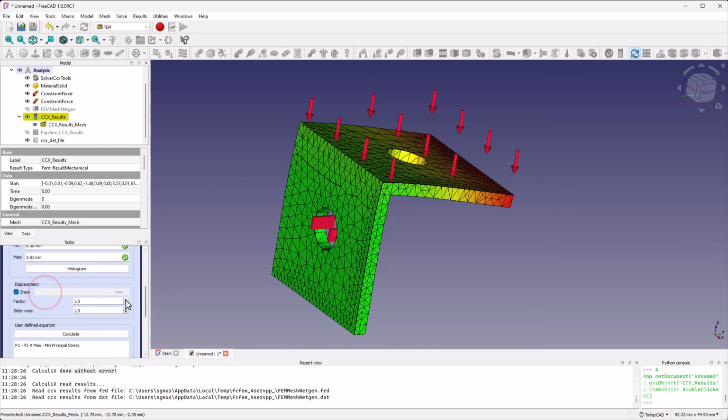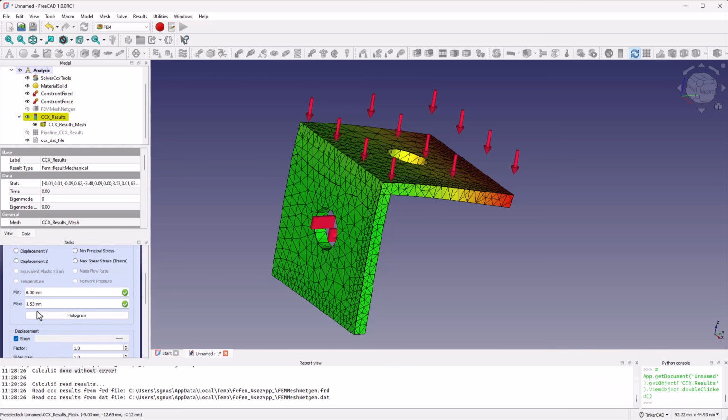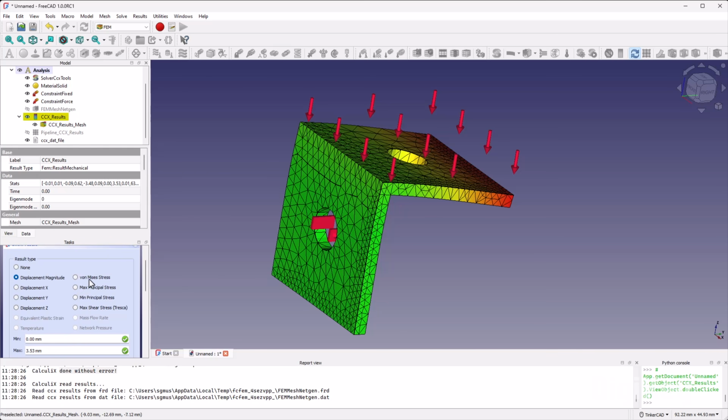So up to 5 kilograms here, you can see it deflects about that much. That's not great for a plastic piece. I would kind of expect that to put a lot of stress and perhaps fracture. The other thing we can do is view the von Mises stress. This allows you to view the total amount of stress, assuming 5 kilograms on top of the bracket.